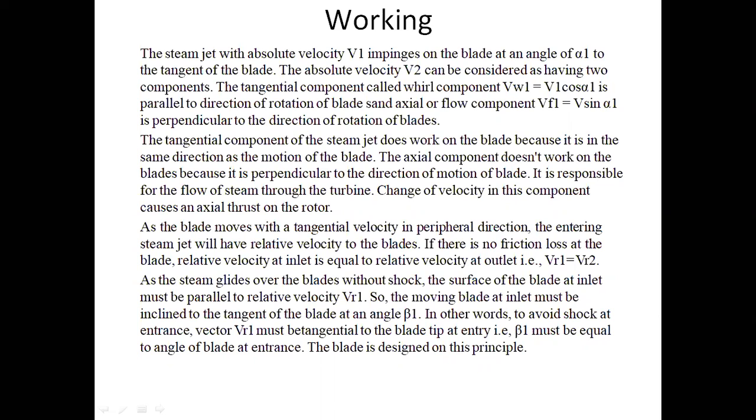So see here, in this working principle, we know the absolute velocity V1 can be considered as having two components: the tangential component called the whirl component and the vertical component called the flow component.